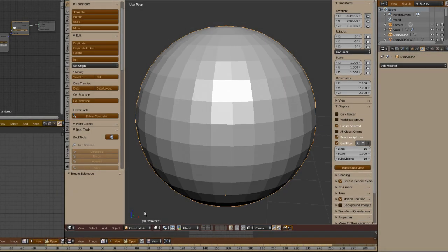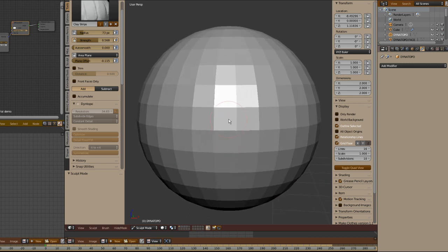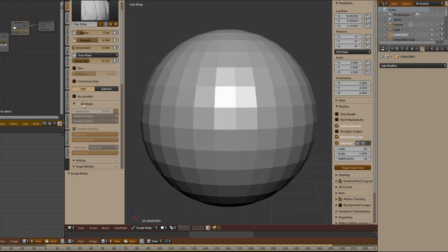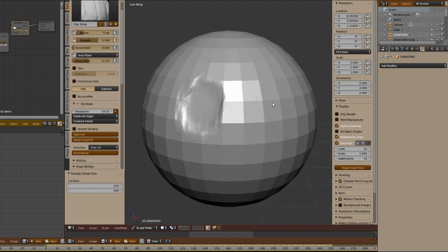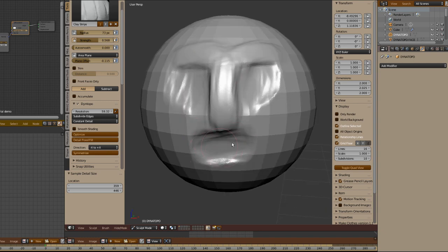Here, the system is different. Let us understand. Regardless of the workflow, in this system I have several ways to accomplish my work, and I can also use several tools, features, and techniques in my favor. Here, the system is completely unified. As you can see, I'm going to get into sculpt mode. I use the Dyntopo functionality that enables dynamic tessellation in the mesh. Dyntopo would be equivalent to 3D Coat's brushes, live clay, or brush with remove stretching.